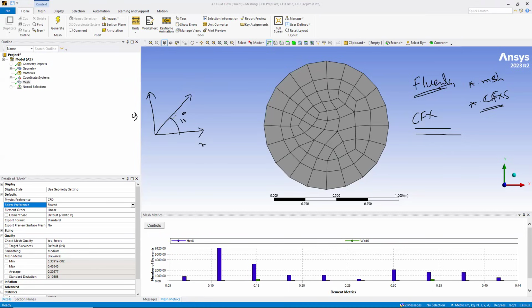Okay. So now if I want to specify the angle of attack in Fluent, I have to give the x component as cos of 10 degrees and the y component as sine of 10 degrees. Very simple thing. Okay. But if I go to CFX, I will either be defining these x and y components, then I will be defining the angle. Like I have to define the angle of attack. Then I will define the x component, that is cos of that angle, then sine of that angle. And then I can specify those parameters in my inlet conditions. Okay. So mostly people don't like it.